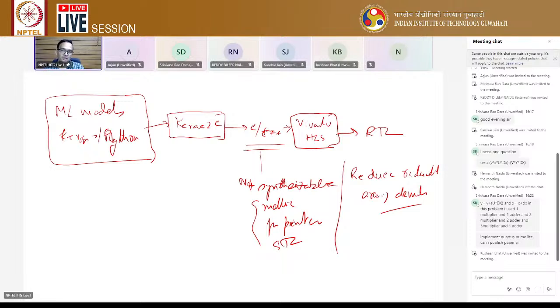Then one more thing is that because these loops are very large, when you try to do the simulation, co-simulation, it will run for a very, very long time. So what we have used is the trip count. You just search the trip count in Vivado HLS.